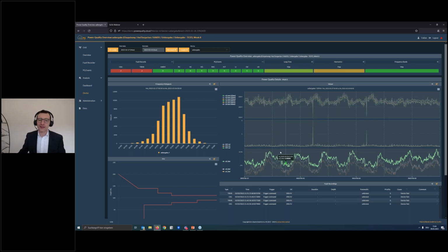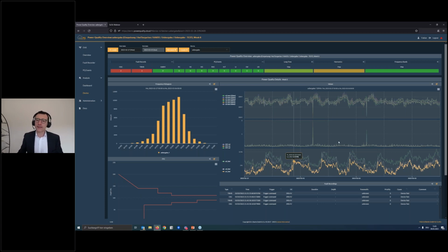So the THD in my house here in my neighborhood is always high if I do not have an ohmic load. And when do I not have an ohmic load? I have no ohmic load, for example, in the night, and this can be seen here. The THD is increasing at night because of the lower ohmic load, and is decreasing during the day because there we have more ohmic load inside our grid. This is a normal situation in many countries as well as many industry companies. If the ohmic load is very low, then the values of the harmonics are much higher, and this can be seen very easily here.